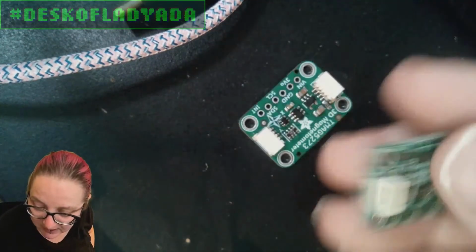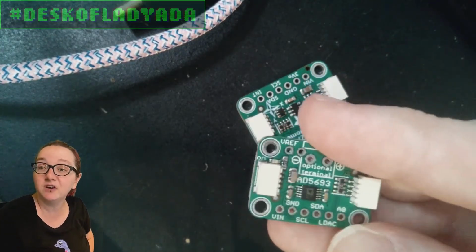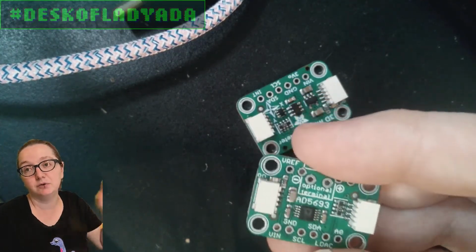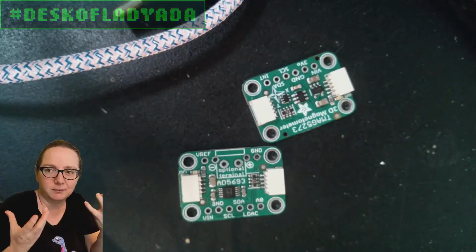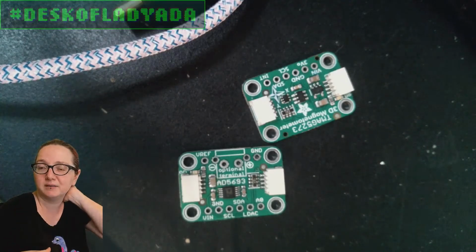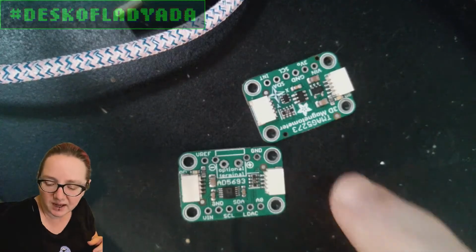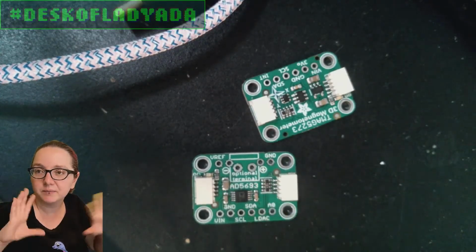And then this morning, this one was actually quite easy, the AD5693. The interesting thing about this is it doesn't use registers. It uses a command byte and then 2 data bytes. There's literally maybe one register called command, and you just write data and then you read from it. But no, sorry, you can't read from it. Or maybe you can read the status. Anyways, I have to check the datasheet, but I started working on this, and I'm going to get that working.